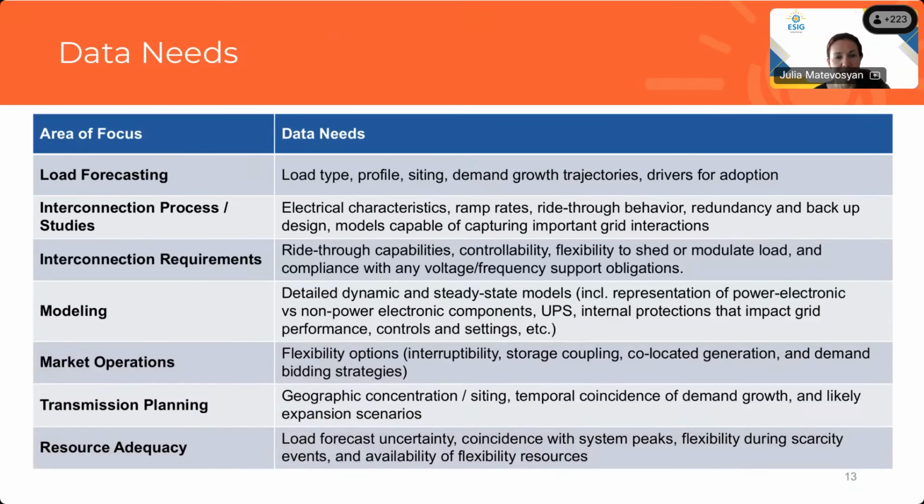Talking about data needs, we tried in each area of focus to identify what the data needs are. Again, we're still finalizing this, but at a high level, for load forecasting you need load type, profile, siting, demand growth trajectories, and the drivers for adoption. For the interconnection process, it's important to know electrical characteristics of the loads, ride-through behavior, ramp rates, what kind of backup, and you need models that you can plug into interconnection studies.